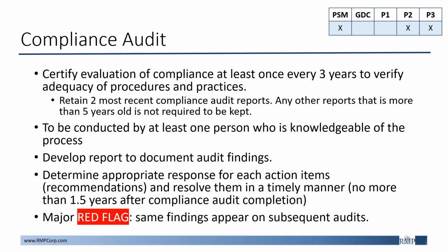A compliance audit is supposed to be like a regular body checkup for the covered process to ensure that all aspects of the process are well maintained and agree with regulatory requirements. Another is if issues were found that were not addressed and documented. Similarly, if an inspector finds an obvious issue that was not addressed in a compliance audit, it shows that the compliance audit was not carefully conducted. One of the compliance audit's most important goals is to find issues in the process ourselves before the auditors or inspector do.